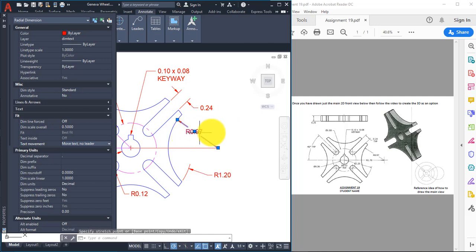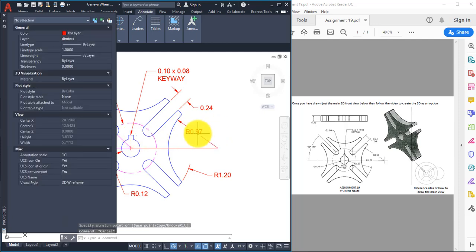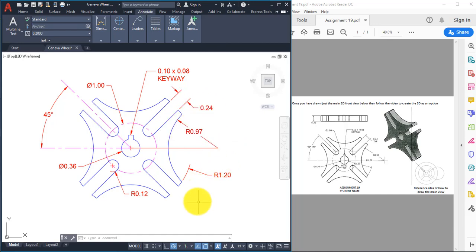When I click, you'll be able to see that there's a line like in the drawing here, an arrow with a line with the text inside. I can use my escape key so that you can see that that dimension is in place. And what they did was they put a little line here to represent the end of or the beginning of this outer arc.